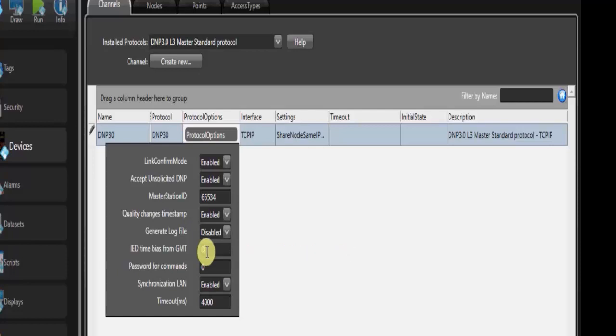7. Password for commands, to increase the security in sending commands, usually initiated only by a change in the state of a tag. It is possible here to specify a password of up to 9 digits, which will be checked by the communication module against the current value when the command is received, with the estimated value attribute of the tag involved in the command. So, in the operation of sending a command through a window, script, etc., this number must be loaded in this attribute. Leaving this option with 0, verification will not be done.